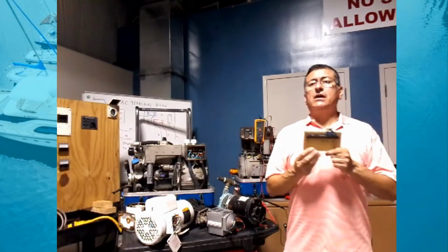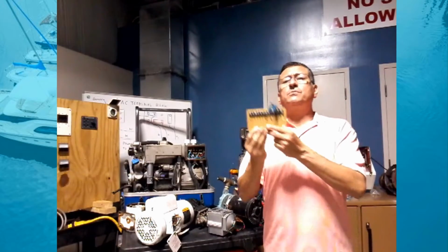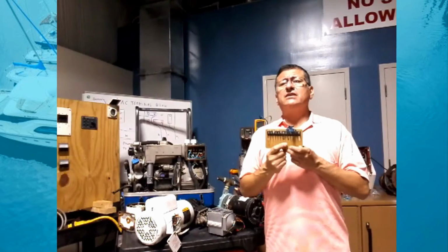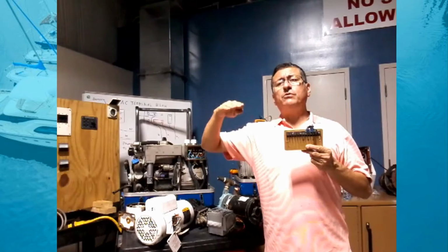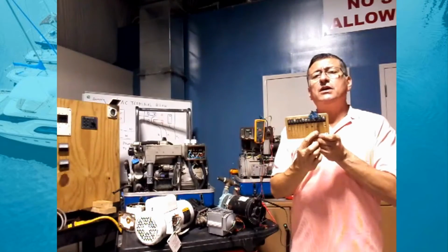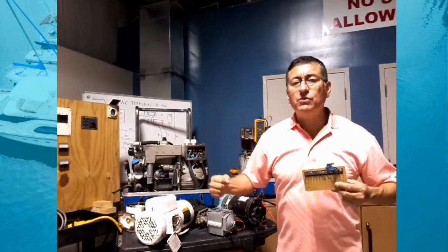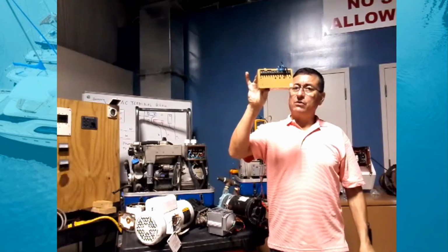That's completely different. Once again, in the voltage regulator, we have three spots. One spot to calibrate output voltage, higher or lower, no more than 10%. The second spot, stabilization, is used to calibrate fluctuation in the output voltage. And the third spot is gain, used to calibrate the time to recover the RPMs. This is the voltage regulator.